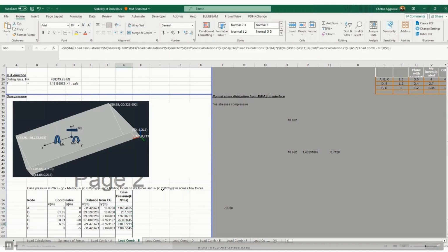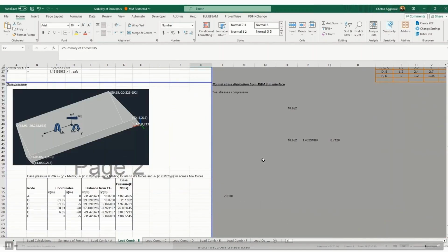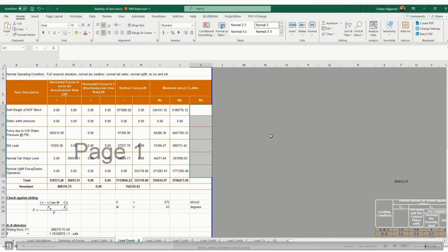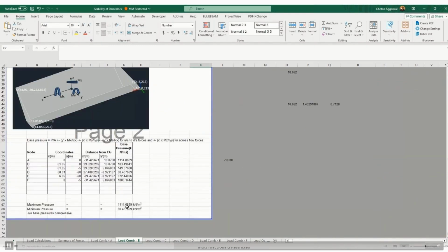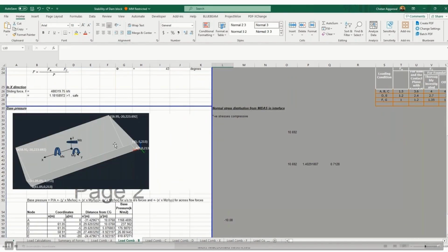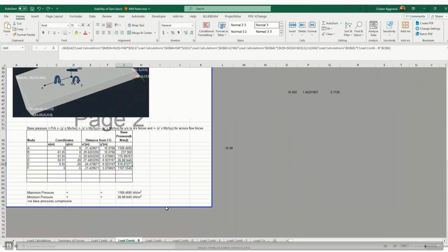If I remove this MZ, there will be only slight change. Okay, say maximum is 1168, the pressure, no? So now it has in fact reduced to 1114. So this torsion effect will have a lesser impact, but it will be there, so I have included it. So in B case also everything is fine, but this pressure is slightly less anyways, but these are all positive. This is what we want. So for other load cases I have to compile the results first, so that I'll do now.